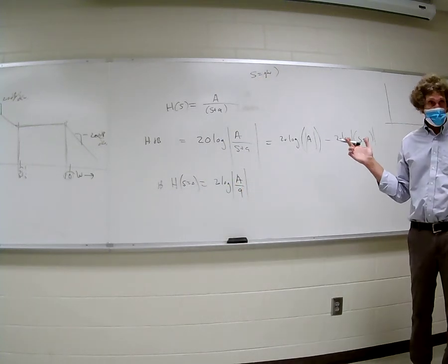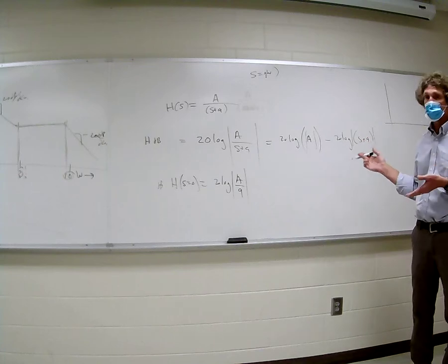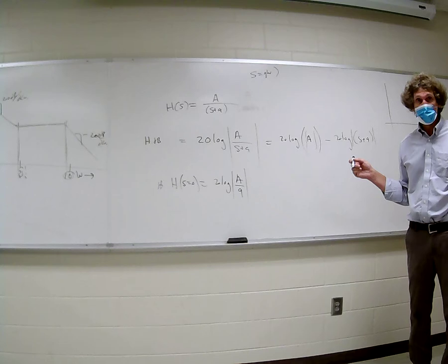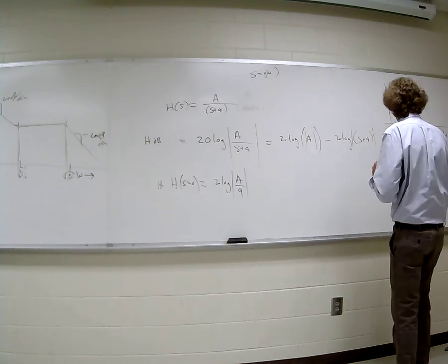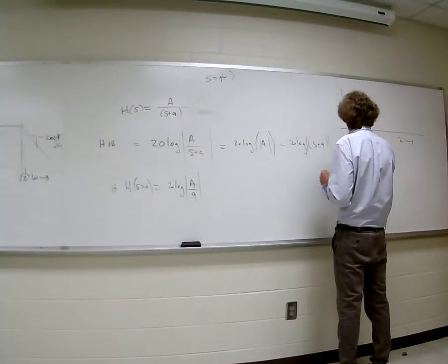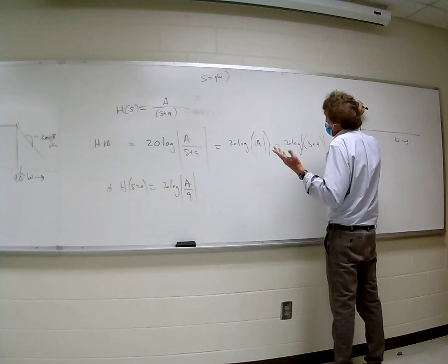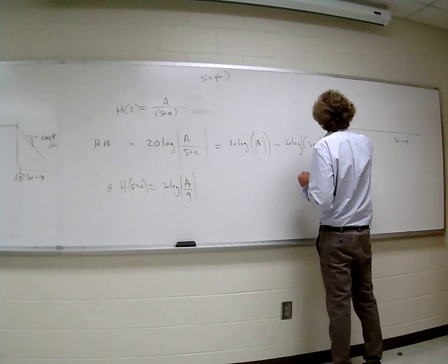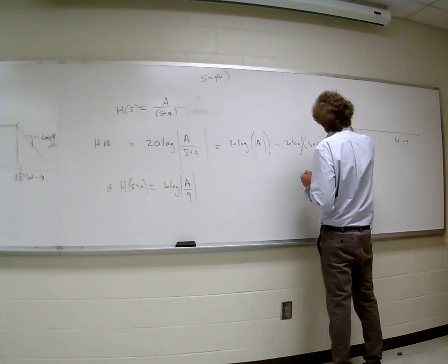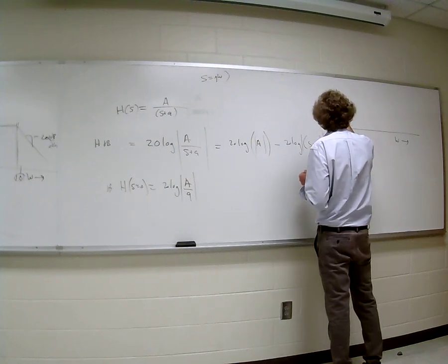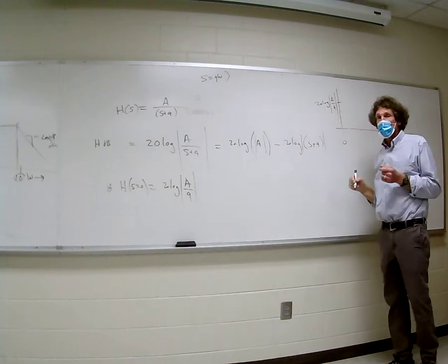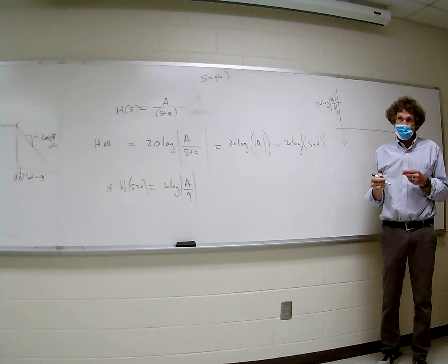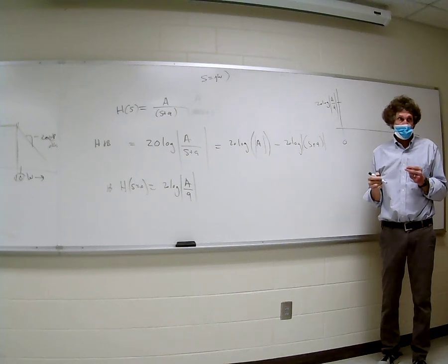Now, I don't know what that value is, but if you give me a capital A and a small a where the pole is, I can tell you. Everybody understand that? That's where you start this thing. So down here, and we can put 0 here. That's where it starts, whatever that is: 20 times the log of the magnitude of A over small a. Capital A could be larger or smaller than small a. It doesn't matter. This always works.